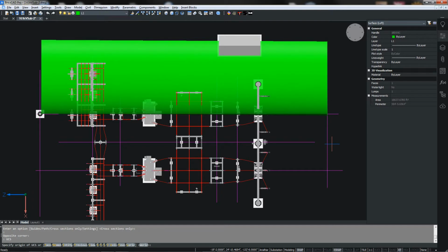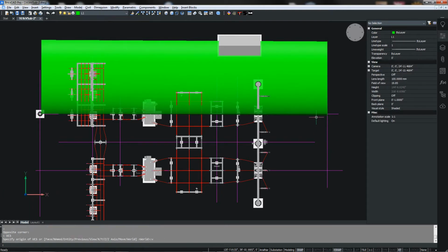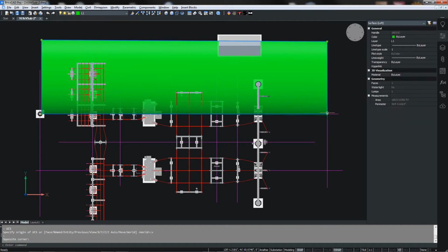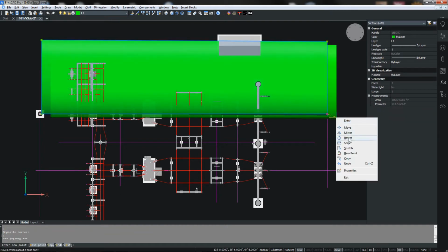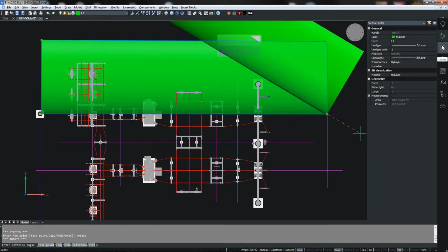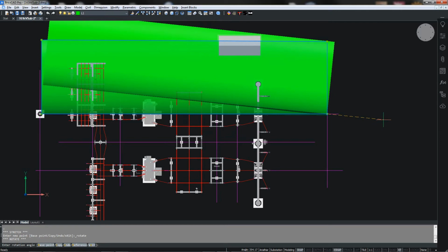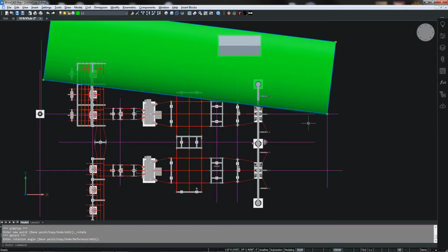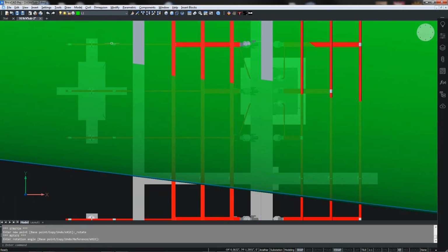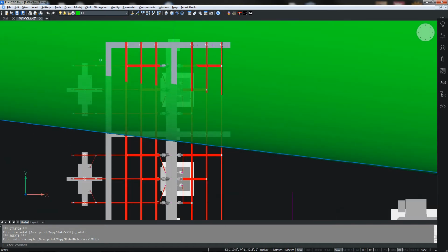So I'm going to pick, let me flip my UCS to the view, because if I'm going to rotate this, I have to be in the XY plane to do that. I'm going to select our surface. I'm going to tell it to rotate. Let me turn this off, and then I'm going to rotate it till I just cover this bus going out to the riser. That's going to leave this bus uncovered, and we're going to look at how we're going to take care of that.